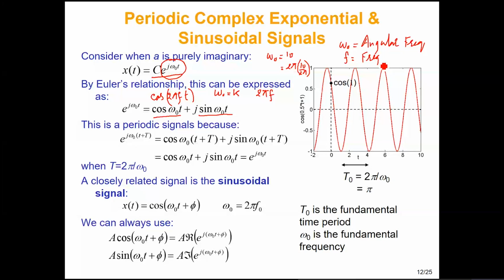And for a periodic signal, because this is a frequency of a periodic signal, we are interested in time period T. And time period T, what is it? It is the repetition time period. And this repetition time period is again linked with both omega naught and f. It is basically equal to 1 over f, or in other words we also call it 2 pi over omega naught. This is the repetition time period in seconds, that is, it repeats itself after how much time duration. So these are basically some linkages which you may already know, but we were interested basically in the complex exponent.